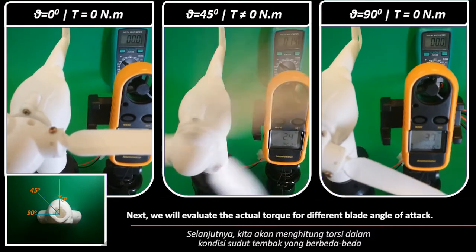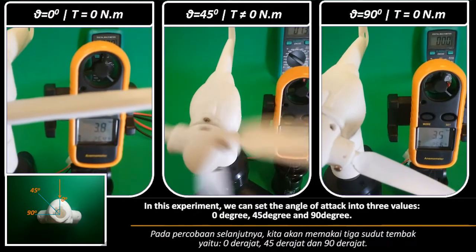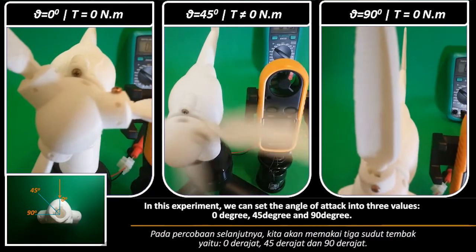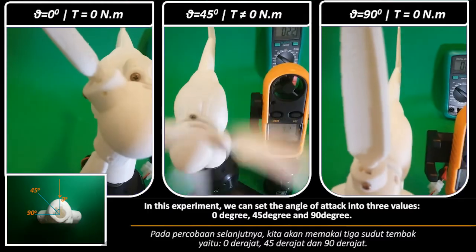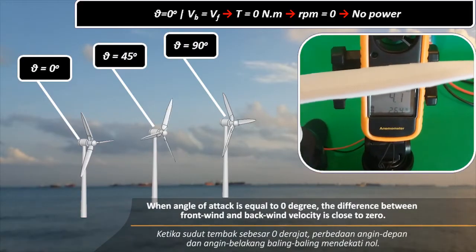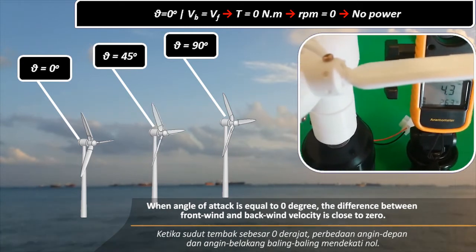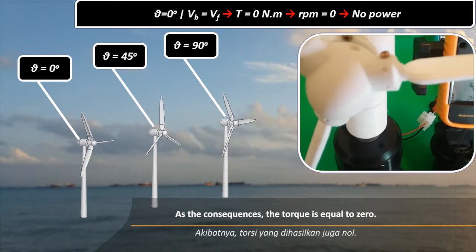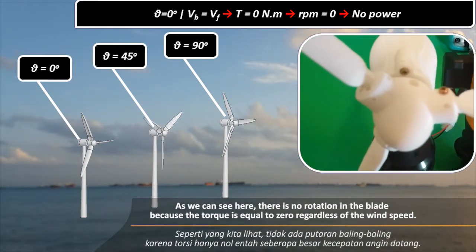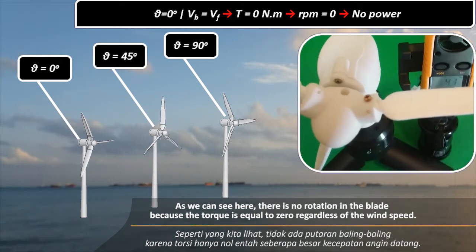Next, we will evaluate the actual torque for different blade angle of attack. In this experiment, we can set the angle of attack into 3 values: 0 degrees, 45 degrees, and 90 degrees. When angle of attack is equal to 0 degrees, the difference between front wind and back wind velocity is close to 0. As the consequence, the torque is equal to 0. As we can see here, there is no rotation in the blade because the torque is equal to 0 regardless